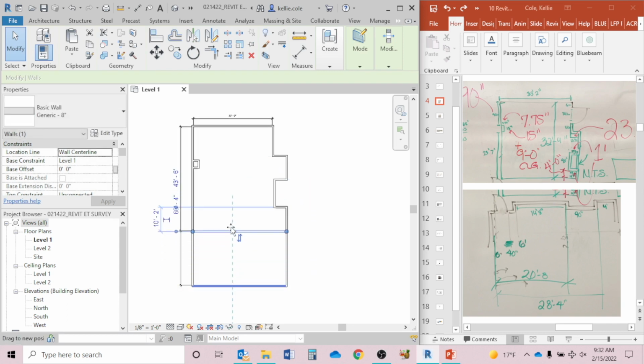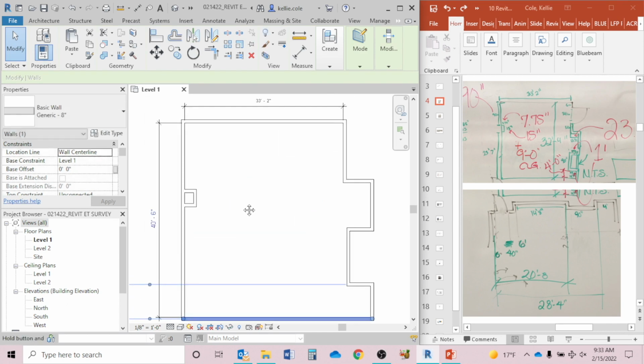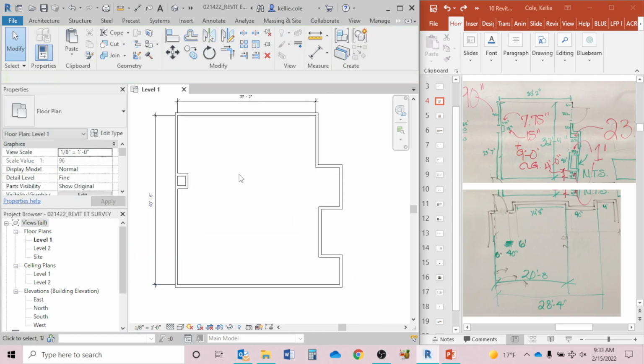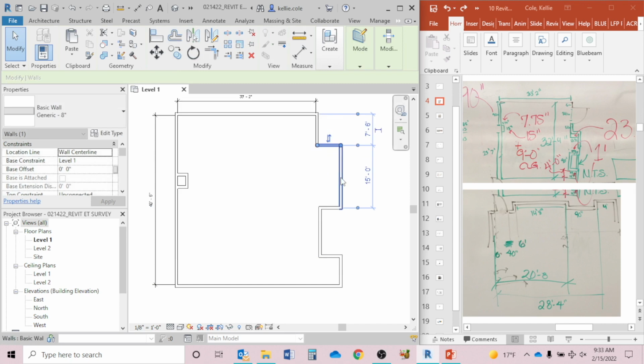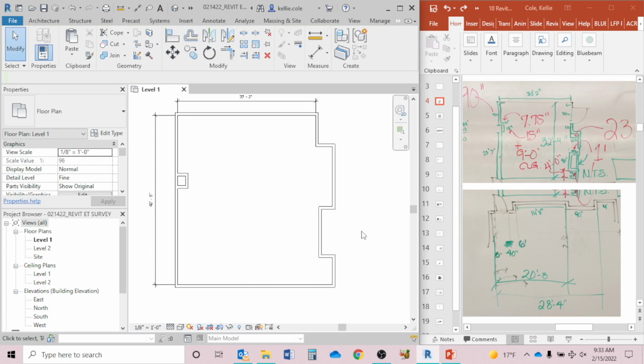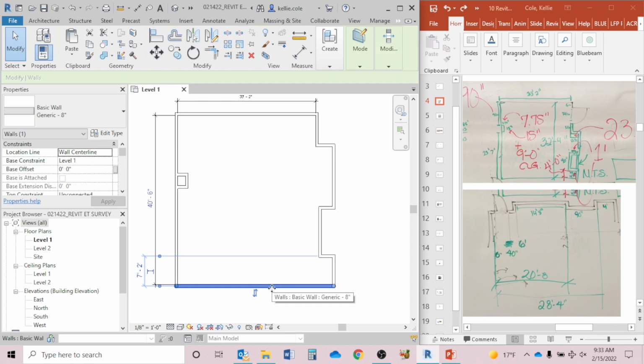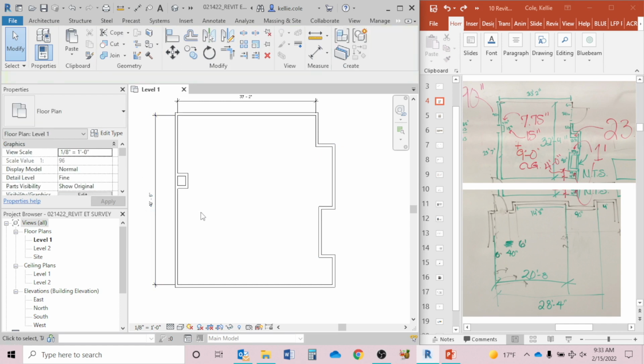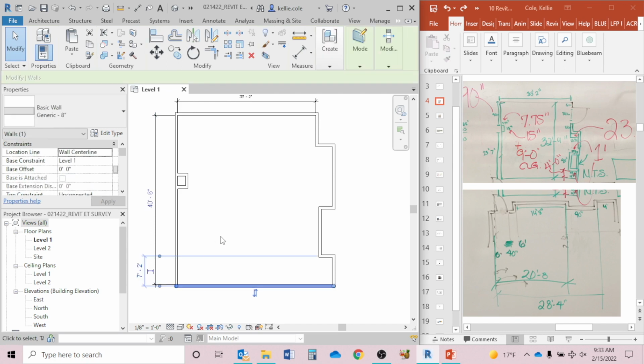Because I realize that I've drawn this really way too large. Okay, so we'll make it a bit smaller compared to that first dimension. Okay. Let's do the second wall. I'm going to touch the bottom wall. I can really touch either one, but I'm going to move it with the dimension I have here on the left. Touch the bottom wall.